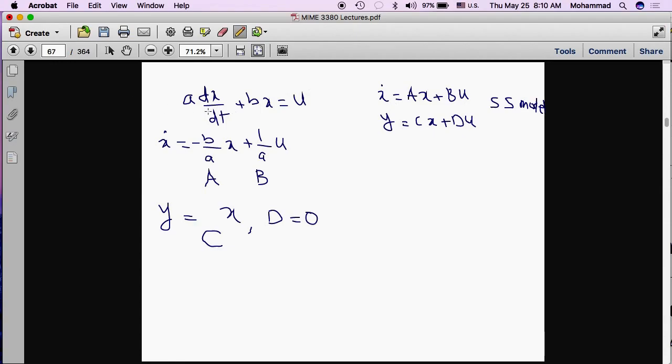And this was the very first practice. We said if this is the model of the system, the first equation on top left, a x dot plus b x equals u, where x is the state variable because it's just one, we can't call it vector. So it's a state variable here. How can we rewrite this equation to resemble the first part of the state space model? The only thing we had to do was to divide this by a, so x dot is just by itself on one side and push everything on the other side. So A, capital A in our case, simply is lowercase b divided by a with a negative sign, and capital B is 1 over a.